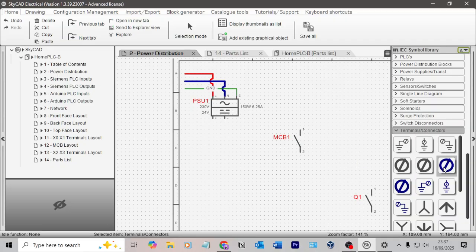So now we have two choices. Sorry, here on these group terminals, these blue ones, or if we go with these specific ones, the grey ones. Terminal referencing terminal strip position, which I think is what I want to use, versus the terminal referencing the wire number. Now I have seen both in the real world, and I can't say which I prefer better.